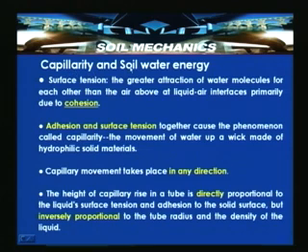So, capillarity and soil water energy: the surface tension, the greater attraction of water molecules for each other than for the air above at a liquid-air interface, primarily due to that cohesion. So, adhesion and surface tension together cause the phenomenon called capillarity. That is what we have discussed. Adhesion and surface tension together cause this phenomenon, which can actually draw the water against gravity and keep it within the pore spaces.